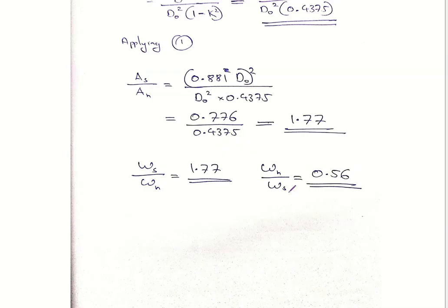So by any index of design, a hollow shaft is way better than a solid shaft, because for resisting the same load, it is taking lesser amount of material. In many cases, the hollow shaft is better than solid shaft because it is consuming less material. The weight is less, and that indicates that the amount of material that goes into it is also less.